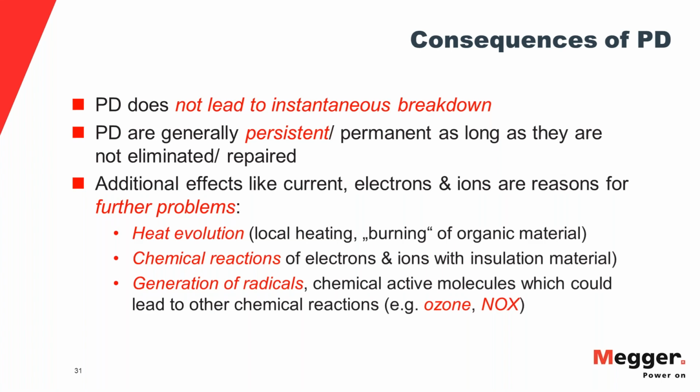Once pretty much everybody, in this case in Europe, adopted VLF testing and got their reliability numbers up, they hit another wall, so to speak. They needed to know more. And that was the transition from preventive maintenance to predictive maintenance with some condition-based aspects.